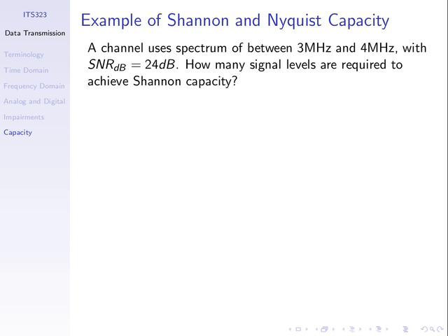SNR dB is the decibel value. A little bit confusing, we use the same SNR. So in this equation, SNR dB is one variable. SNR on its own is another variable. This is the absolute ratio. This is the value in decibels. And this is the same equation that we have over here. The general decibel equation, 10 times the logarithm of two power levels, the ratio between two power levels. In gain, it's 10 times the logarithm of P out divided by P in. In loss, 10 times the logarithm of P in divided by P out, and so on.